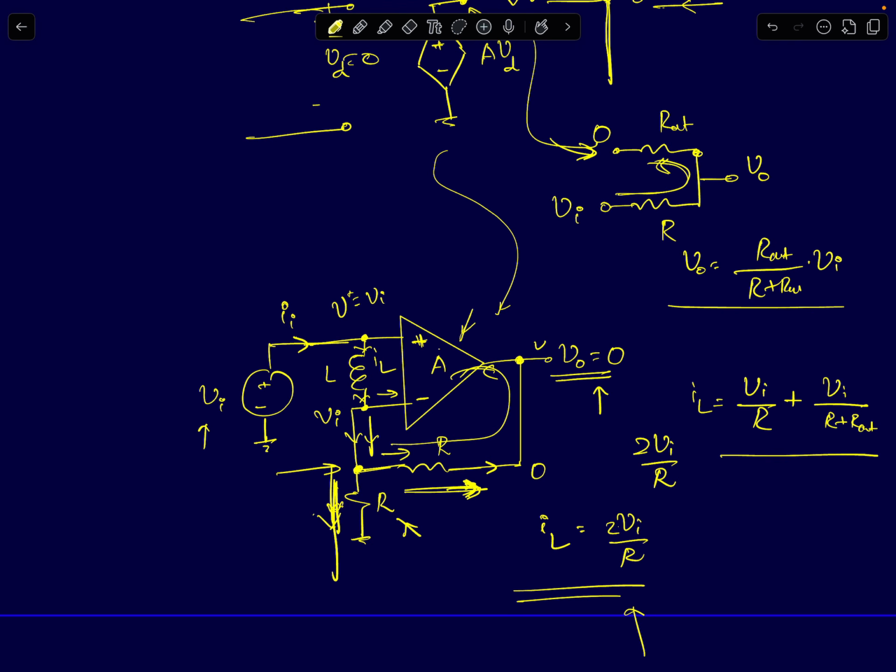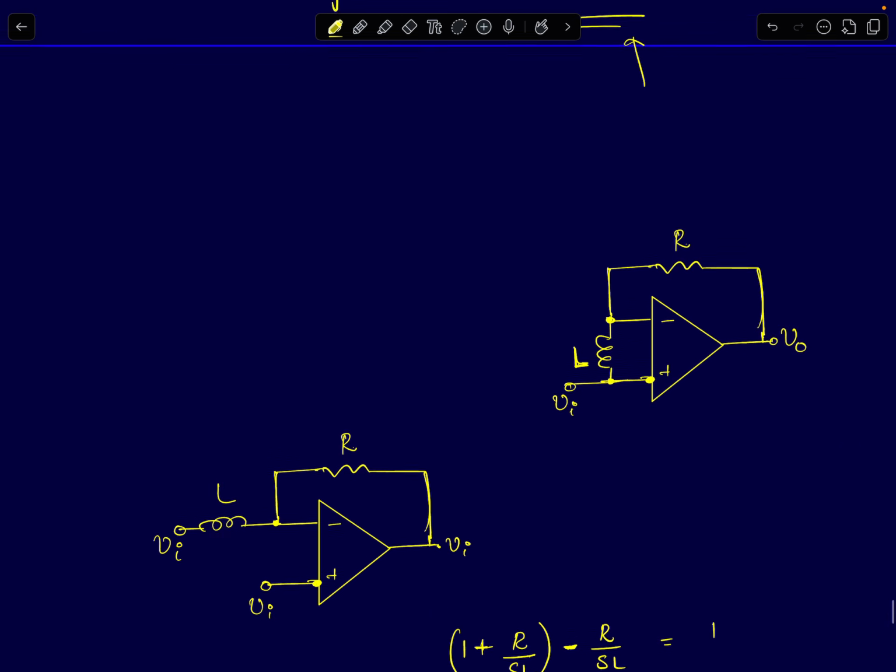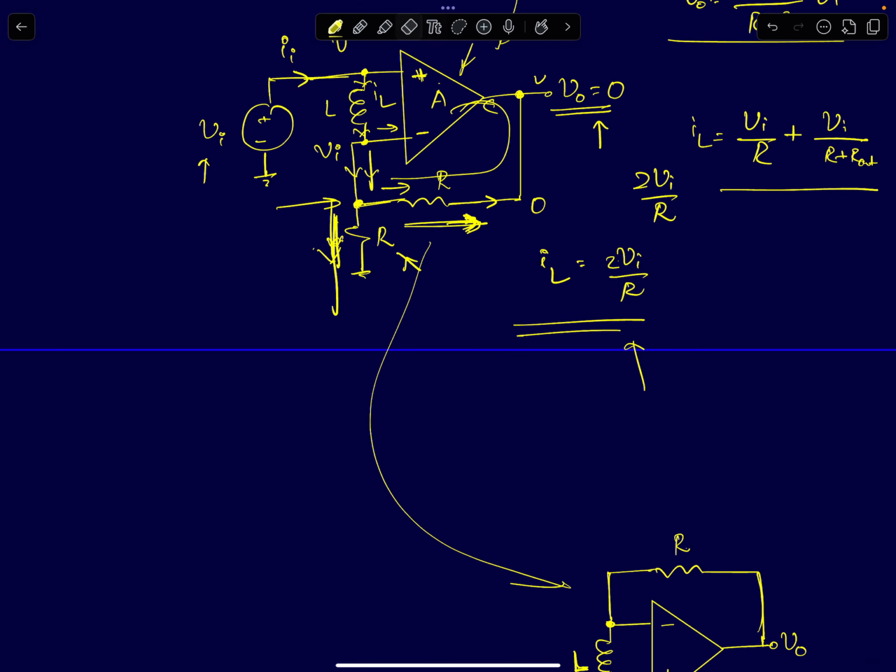That's why it's a hypothetical circuit, and you will actually see that if you assume your op-amp to be an ideal op-amp, which is not a practical possibility, your output voltage will come close to 2 Vi. I'll do the exact mathematical analysis later, but what I'll do is analyze a similar problem, slightly a reduced version. I'll just remove the resistor on the inverting path. It's the same circuit. I just redrew the same circuit here, just that I've removed this resistor.